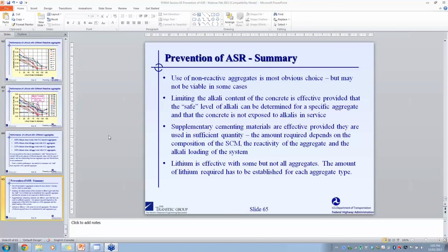With petrography, then, yeah, I guess that's been a little bit more successful to the extent that we know that our highly reactive forms of opaline silica will react at relatively low alkali contents. And I'm talking about maybe around 3 pounds per cubic yard. But some of our aggregates that react because of microcrystalline quartz or strained quartz, such as graywackes, may require in excess of that amount.